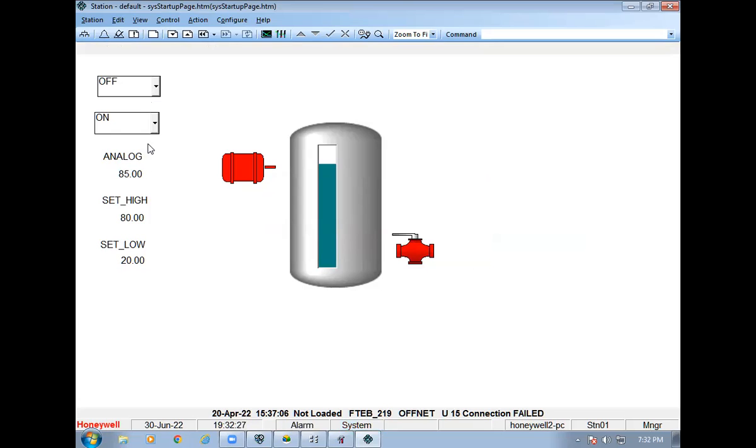So now I'm going to give a set point of below 20. Only one click is enough here. Okay. No need to give a double click. 20. Then I'm going to enable my start input here. So at that time you can see my motor should be started. Okay, motor started. Yes, sir. Then I'm increasing the value. So I turn off that start, but it will be still on. Then I'm increasing the value to 50.